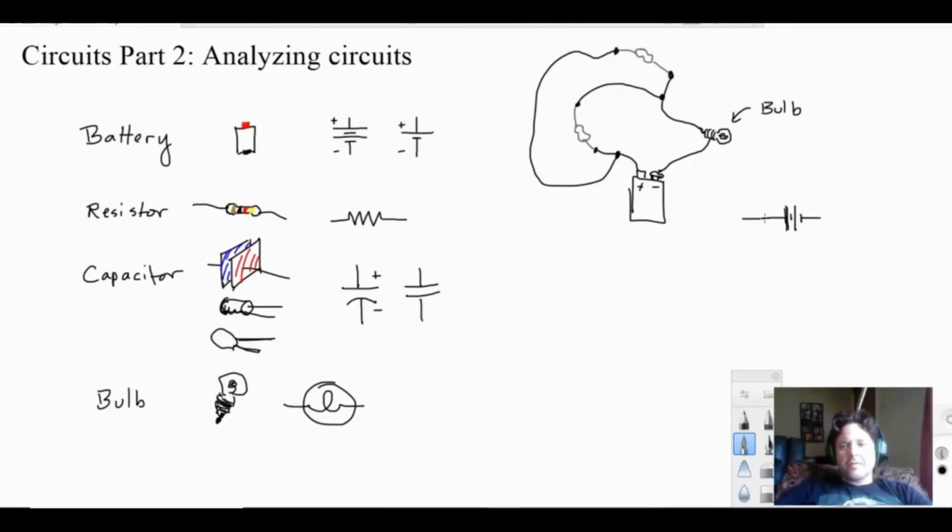So we have one resistor that is attached to the positive terminal of our battery, and then you can see here that another is connected directly to the positive terminal of the battery. One easy way to keep track of this is to look at that node or that circuit segment where we have nothing but wire in here, right? All the way up to these two resistors. We can even label them resistor 1 and resistor 2 and then write them accordingly in our circuit.